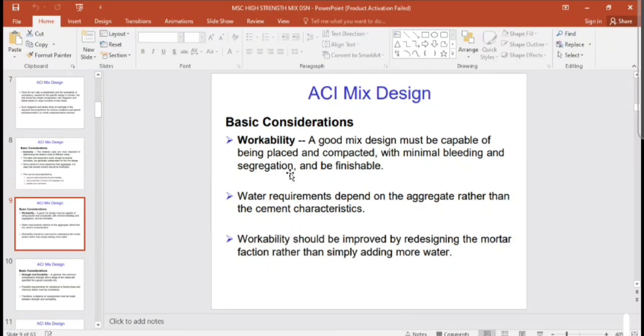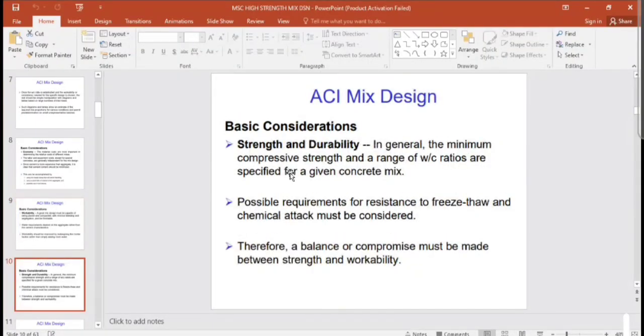Code says that your slump value as per ASTM C143, the test regarding the slump, should be 2 inch to 4 inch. So minimum 2 inch should be there. Slump value is from our inverted cone test. So our mix should be workable. Then at the last we place it, but it is the primary one.